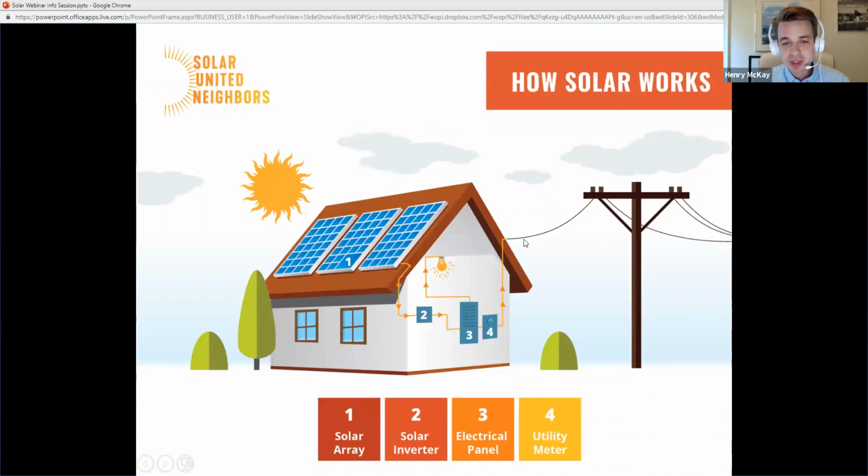So all of these components together, the solar panels, the inverter, this is how they work. So let's imagine it's a really sunny day. Your panels are drenched in sunshine, and maybe you're out of the home, so you're not really using that much electricity. So your panels are going to generate DC electricity. It's going to travel down to your inverter. So that's number 2 here on the flow chart. Your inverter is going to switch that from DC into AC, and then it's going to send that AC electricity into number 3, your electrical service panel, and it's going to go into your home.